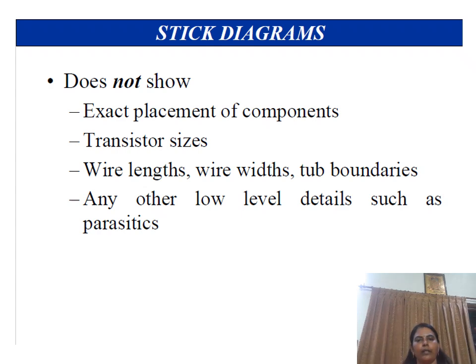Stick diagrams do not provide detailed information about the chip, which means they don't give the transistor size, that is the W by L dimensions, the width and length of the transistor, and they also won't give the wire length, boundaries and other details.